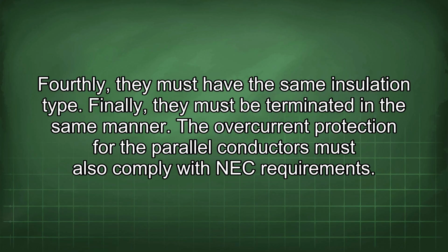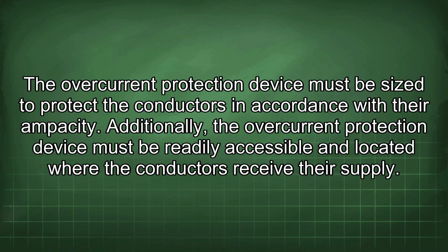The overcurrent protection for the parallel conductors must also comply with NEC requirements. The overcurrent protection device must be sized to protect the conductors in accordance with their ampacity. Additionally, the overcurrent protection device must be readily accessible and located where the conductors receive their supply.